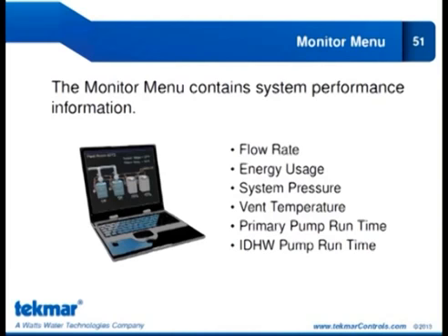If I can find one, the Badger one, to see if it works. For example, it's like an insertion style. So you're not looking at a body measuring the flow. Instead, you're inserting a turbine into the pipe. Yeah. And one thing is that can be hot tapped, which is nice. But the other thing is that I think it's either a 1/2 or a 3/4 inch insertion. So that might be more flexible.